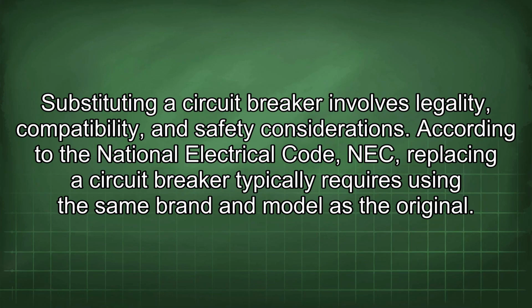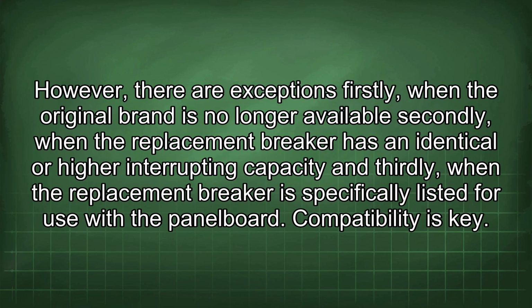Substituting a circuit breaker involves legality, compatibility, and safety considerations. According to the National Electrical Code, NEC, replacing a circuit breaker typically requires using the same brand and model as the original. However, there are exceptions. Firstly, when the original brand is no longer available. Secondly, when the replacement breaker has an identical or higher interrupting capacity. And thirdly, when the replacement breaker is specifically listed for use with the panel board.